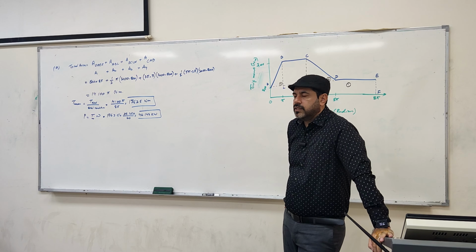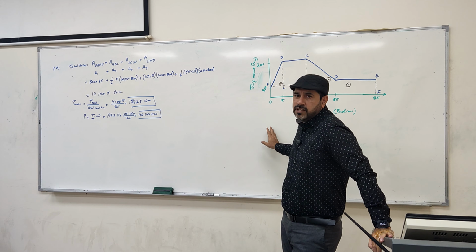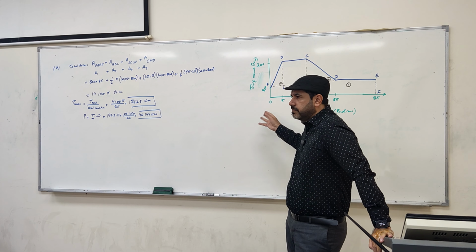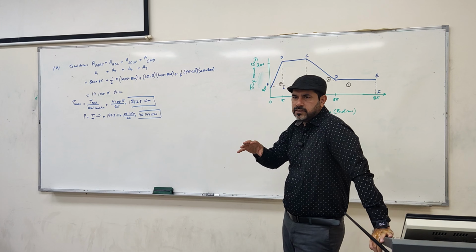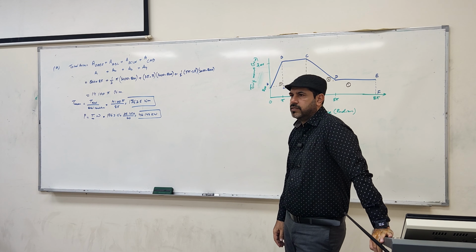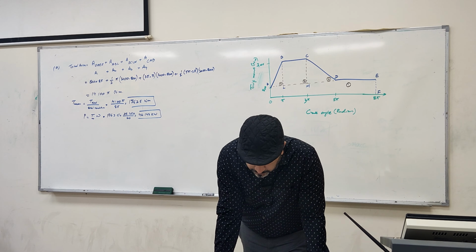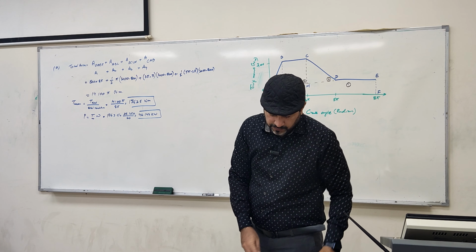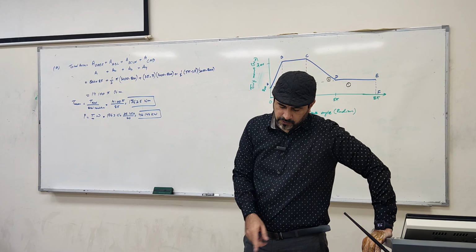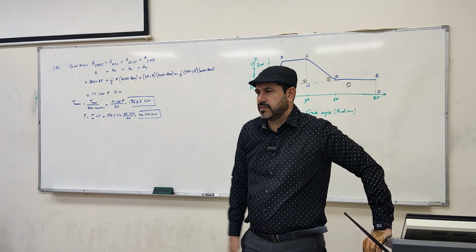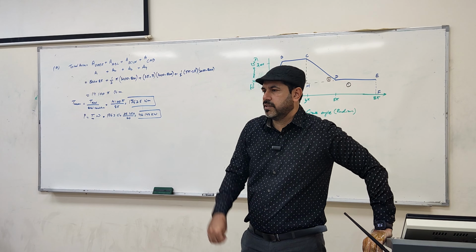So you can see, seems like the discussion was very complex, but the numericals are very easy because all we need is to make this composite diagram into smaller pieces and then find out the area under it. Yeah, that's a typo error. This is what I said. The last 1.5 revolution, the torque is constant. And you can see why it is a typo error, because it says 4 revolution. This is only possible once you add these. Otherwise, if it is half revolution, you end up with 3 revolution. All right.